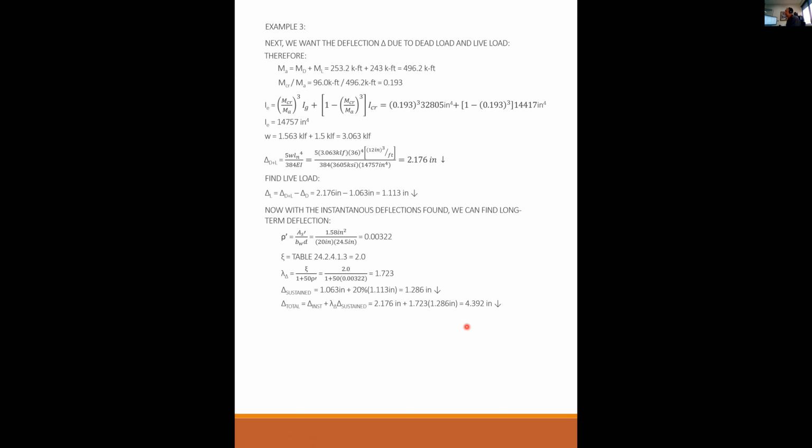Well, this beam would have passed the phi Mn. Phi Mn is greater than Mu. So this building can be in service for 50, 75 years, and it would never fail, in the sense that failing is that the beam's falling down, it's yielding, it's completely failing. It may never fail, but it just has a deflection that is uncomfortable.